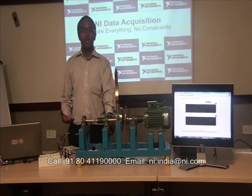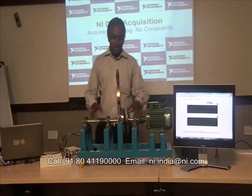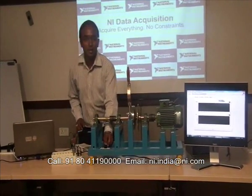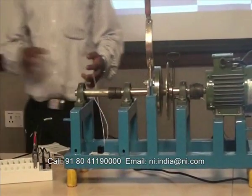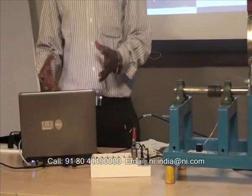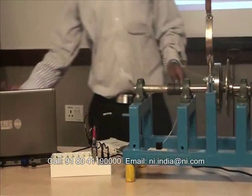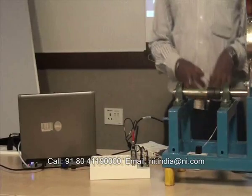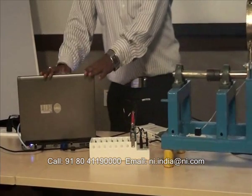real time. Machine condition monitoring applications have been used in industry from structural health monitoring in the case of the Beijing Olympics to probably a simple rotor or a fan application in our regular household products. In this setup, apart from this machine which is replicating the industry environmental conditions, I have a sensor or a transducer. This transducer is capable of capturing the real-time vibration data and sending it to the computer. The computer is used for any kind of analysis on the real-time vibration data. Now, this sensor cannot directly give the data to my computer. It has to go through an interface device in between which can take care of capturing this data and transmitting it real time to my computer.